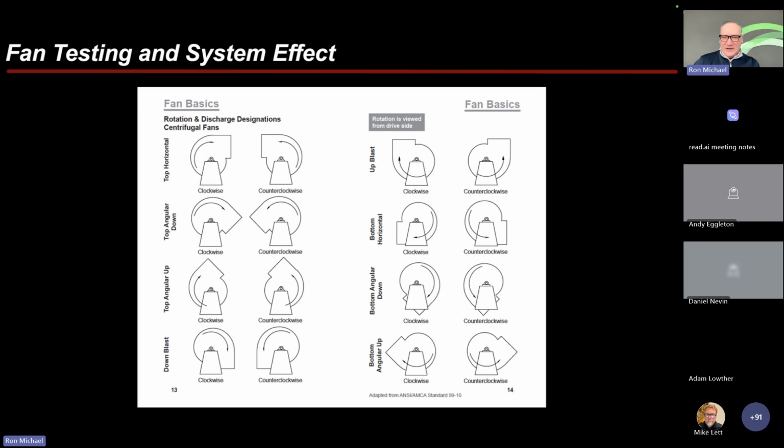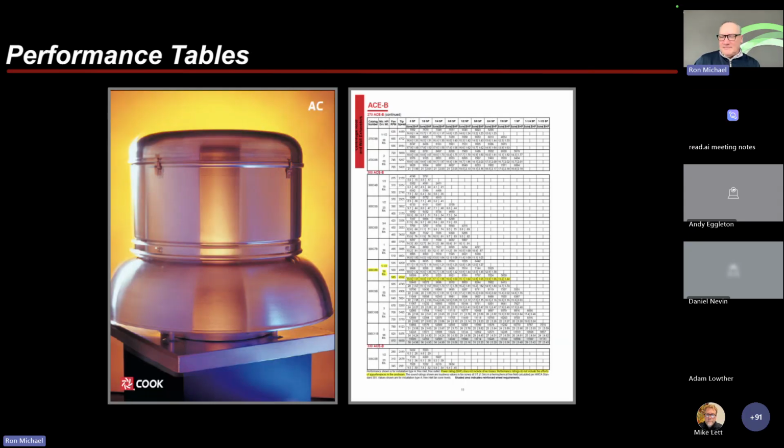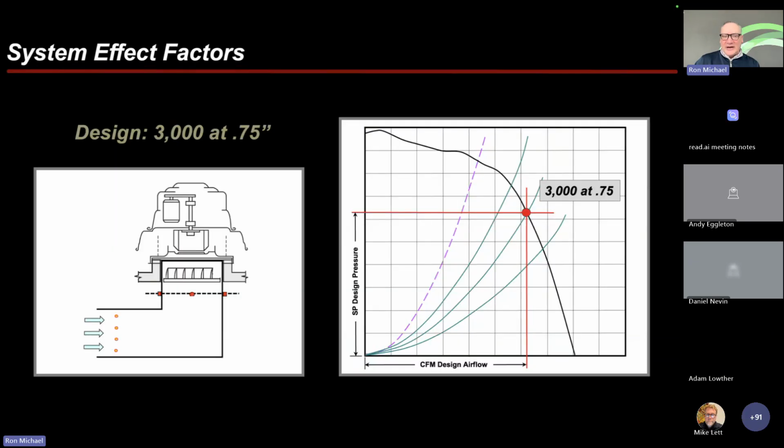So you're going to understand. I'm going to try to give an understanding of how important this sheet is. And for any young engineer, it's one that I would literally hang up in my workspace, especially for the young engineers working in Revit. Okay. So again, we come back to the beginning. It's all about performance tables. I remind everybody, no matter how good your calculations are, if you pick the wrong fan or pick it on the wrong fan curve, you're really going to run into a lot of trouble.